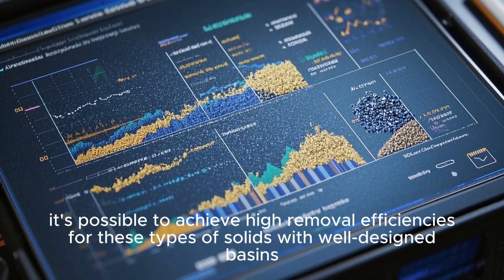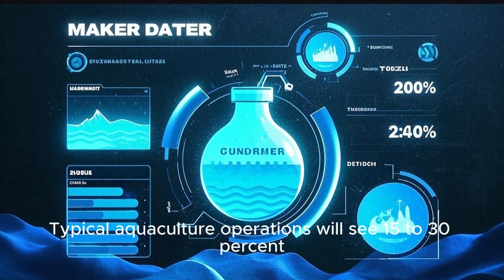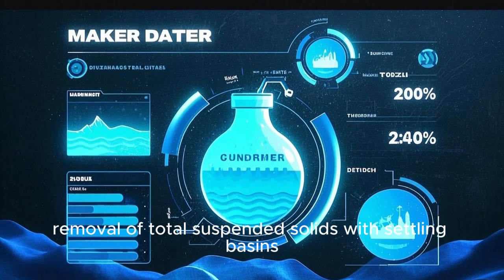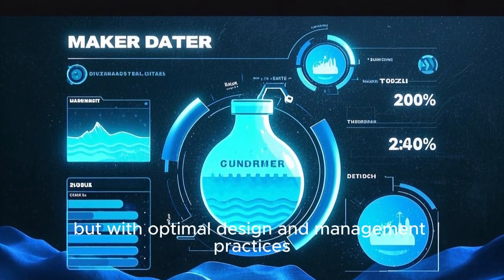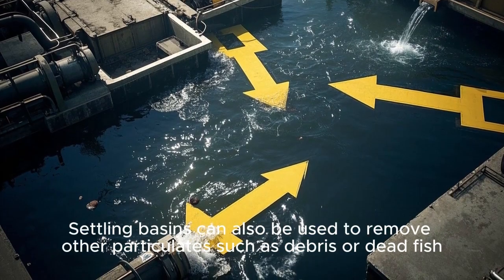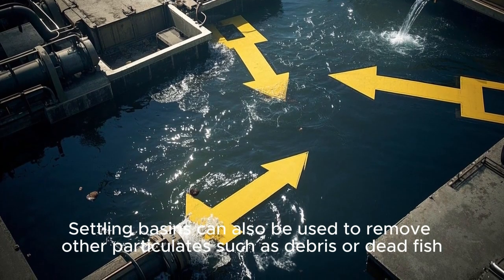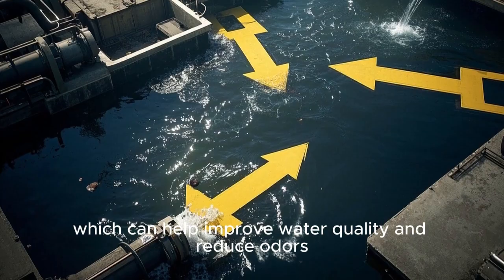With some particle types having very predictable settling characteristics, it's possible to achieve high removal efficiencies for these types of solids with well-designed basins. Typical aquaculture operations will see 15 to 30% removal of total suspended solids with settling basins. But with optimal design and management practices, removal efficiencies can exceed 90%. Settling basins can also be used to remove other particulates such as debris or dead fish, which can help improve water quality and reduce odors.